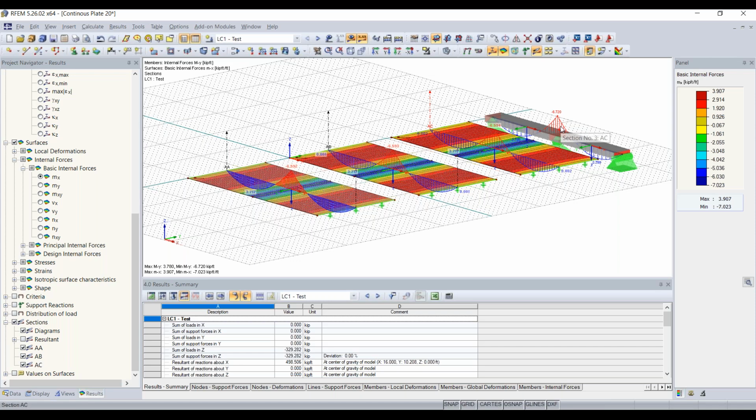The reason that this change happens is because the methods mostly used in school assume that each member has an infinite shear stiffness, when in reality there is some shear deformation happening when members or beams bend. So it's important to keep this in mind again when comparing hand calcs.